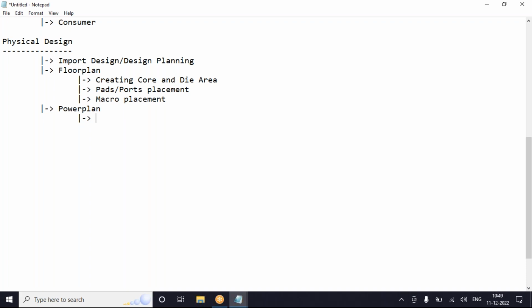Okay, so the first criteria is to make sure the macros get enough power, such that when it comes to the internal area other than macro placement, there will be an extra area for the standard cells, right? Small rooms. Will there be enough power for it to be passed properly or not? Without placing those cells, I'm checking it. After placing it also, I have to check it. First, I'm making it assured. Will I be able to have enough power or not?